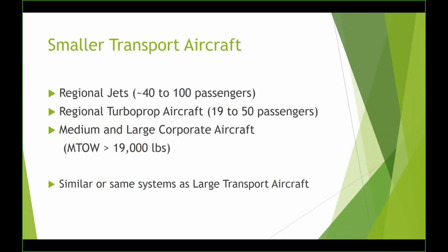Now, there are more stringent requirements for bigger airplanes that carry more people. You may have to have a little more redundancies. If you're flying over open water, over oceans, there's an additional set of regulations you have to follow because you don't have diversion airports as close. But they're going to have similar stuff.